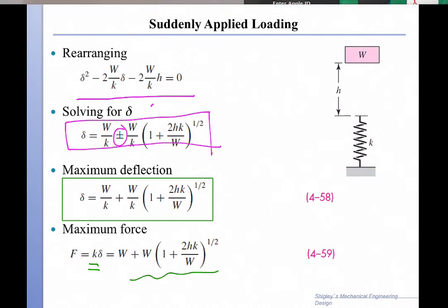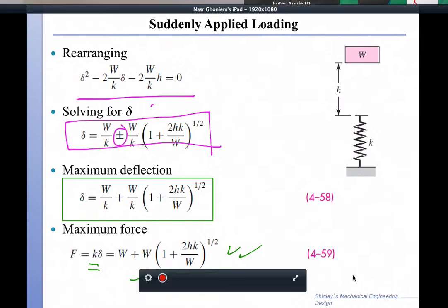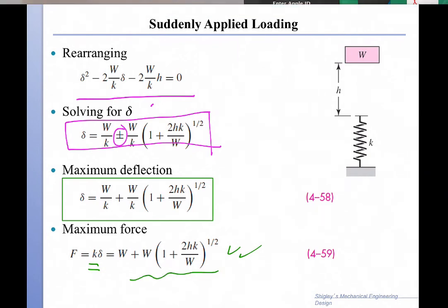Of course, this is approximate because we ignored any dynamics in this situation and it is basically a quasi-static calculation. However, this can be very useful because if I have a finite element solver, I can use this force and then determine deformations or approximate deformations